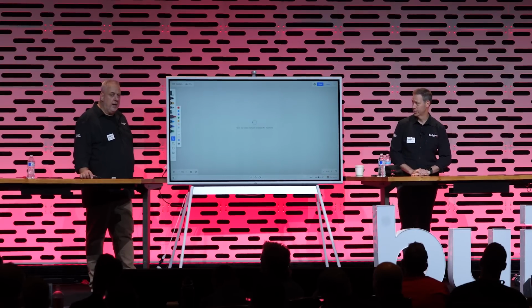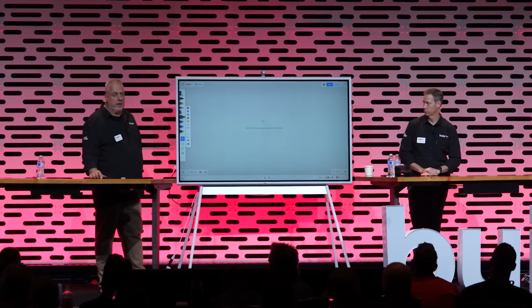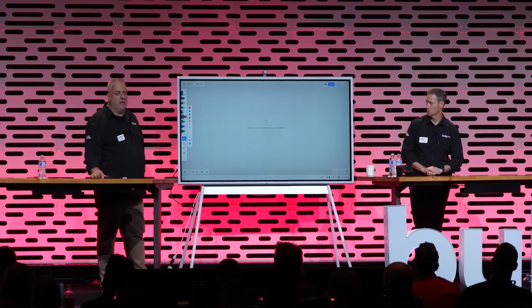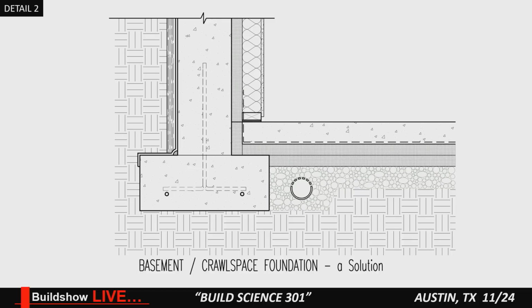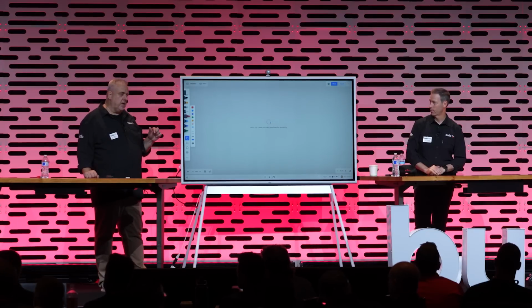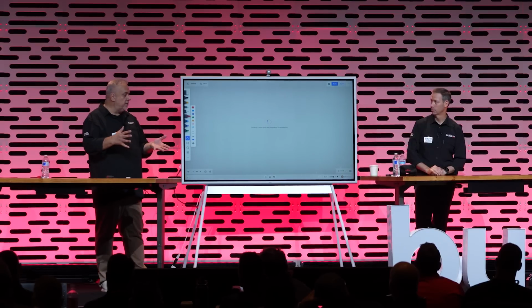Well, first of all, in any moisture problem, we get rid of the water as much as we can. Outside of the wall, in this case here, we have a drainage mat, 60 mil waterproofing system that goes down over the slab or over the footing. Notice there's a little fillet drawing in there. In this particular case, we actually used, there's a company that makes a little bentonite. It's actually a little square cube that you can put in there, and when the water hits it, it swells and basically seals that joint.